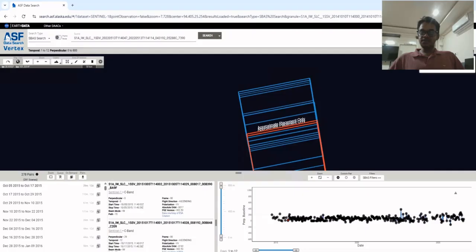That means using the SMAP, Soil Moisture Active Passive satellite data, which will give you the soil moisture, both the surface soil moisture and the root zone soil moisture. With this, you will try to understand what the soil moisture was before the landslide happened. Is that a cause of landslide?